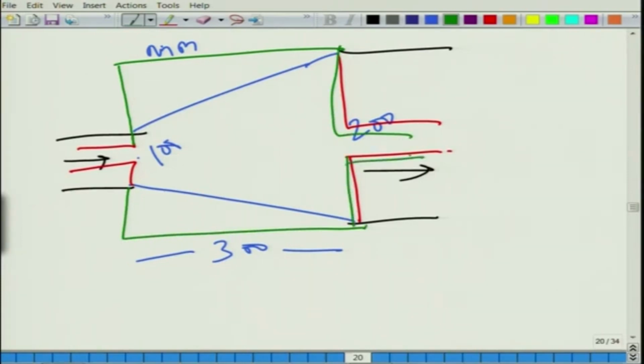So, you see that produces a better performance, but it also has dips at certain frequencies. So, conical chamber, gradually varying area chambers, conical being one of the cases, has an advantage that it can get rid of the troughs at certain frequencies.